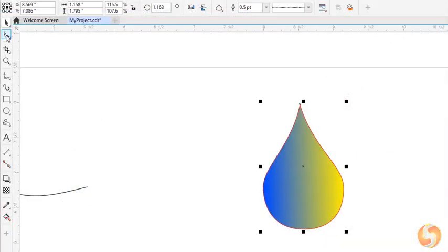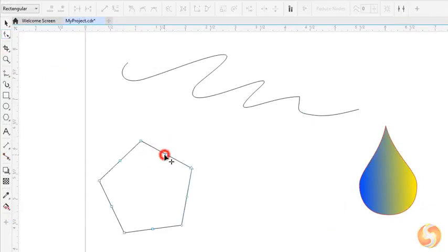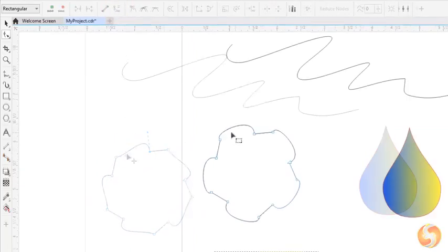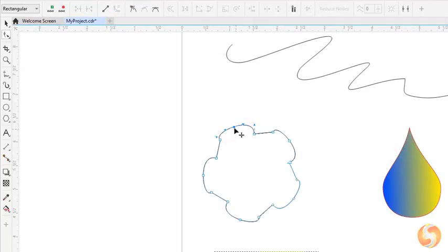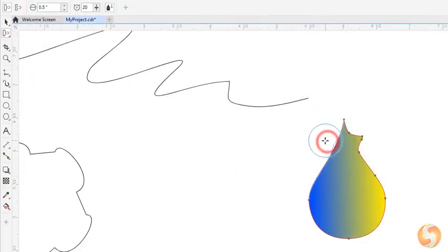To edit the vector shape, you can use all the tools collected inside the second button of the toolbar. With the Shape tool, you can move nodes and tangents to refine the vector shape and double-click on it to add new nodes if necessary. Enable the other tools to apply nice effects by clicking and dragging over the vector paths.